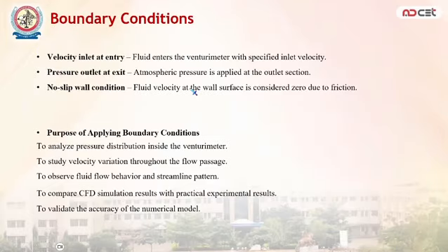The next slide is about boundary conditions. For the simulation, we established three primary boundary conditions. We defined a specific velocity inlet, an atmospheric pressure outlet, and applied a no-slip condition along the pipe walls to account for fluid friction. The setup was critical for accurately analyzing how the pressure and velocities vary.